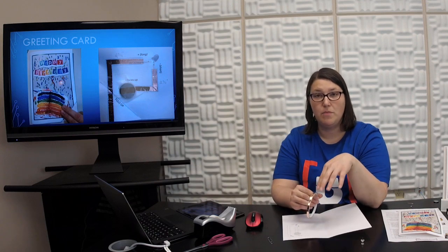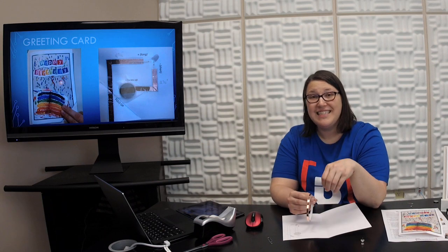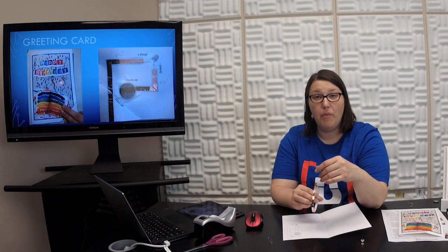All right, so to create our greeting card, the first thing we need to do is lay the copper tape down onto our card. Oh, and something I forgot to mention. With the copper tape, you want to make sure that the adhesive copper tape you buy says that it's conductive when you purchase it. If it doesn't say that it's conductive tape, it won't allow that current to flow, and so you'll end up with a card that won't work. So always test it out after you buy it. Make sure you got the right stuff.